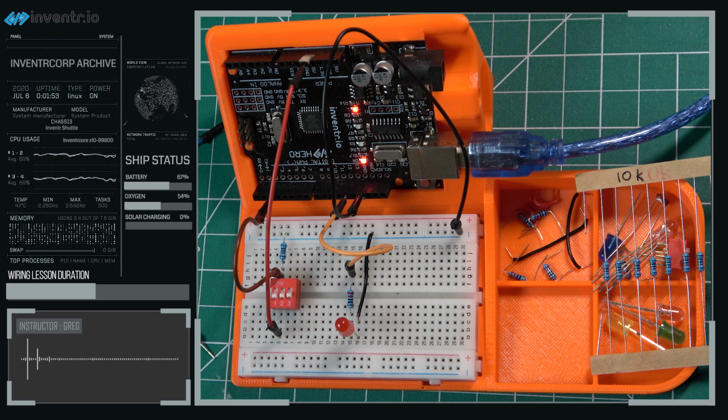Now, I want to make a quick note here before we move on. Our selection here to use a brown wire was completely arbitrary. Depending upon what colors you have available in your parts kit, you might choose to use a different color. Apart from trying to adhere to the rule of using red for positive supply and black for ground, you should feel free to use any combination of jumper wire colors that best help you organize and understand your circuits.